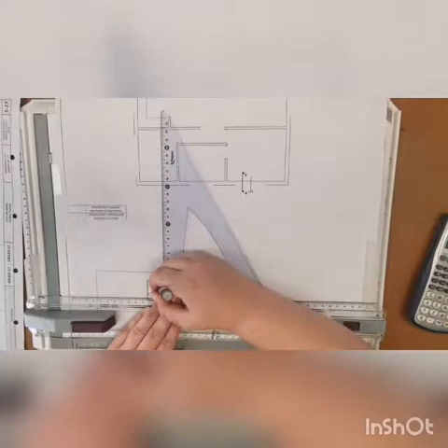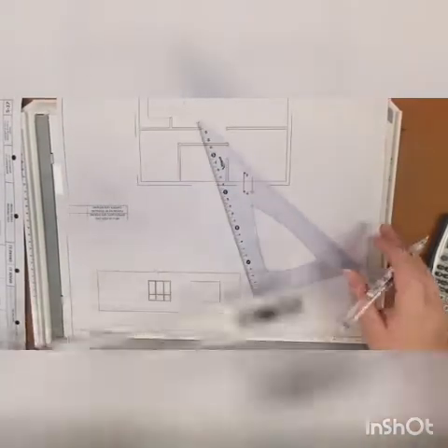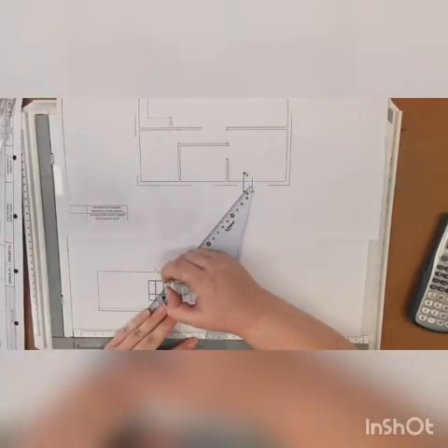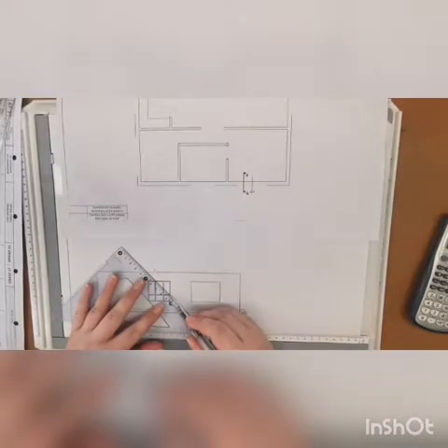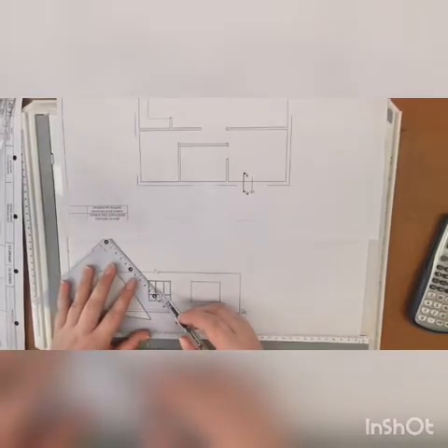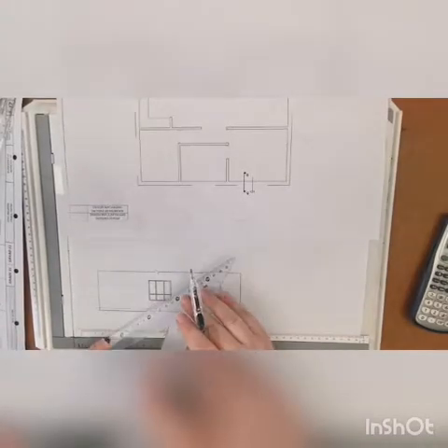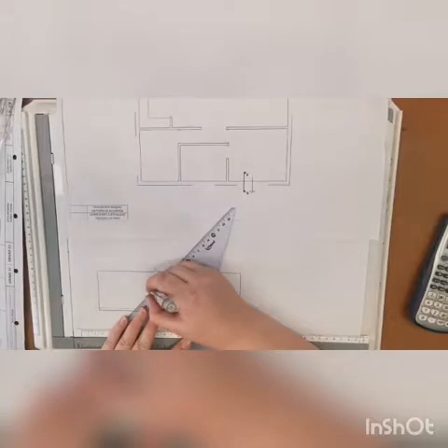Measure halfway, make a dot, and we just lightly, I would actually put it in as hidden detail. Remember, this is just light. Just to show whoever's reading this elevation that this window opens in this direction, and that the rest of the windows that don't have this do not open.